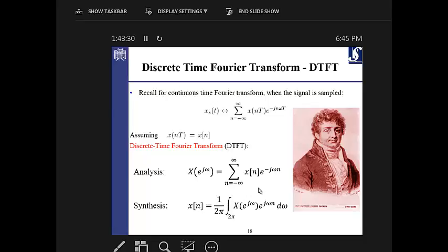I will stop at this point by just giving you this hint: because DTFT is analog, we go through another sampling, which takes the samples out of the DTFT, and that's called DFT. So DFT is nothing but taking the samples from the DTFT of the signal in the frequency domain, and that's something you can use in DSP. But it will remain for the next lecture, which is tomorrow, 10:30.